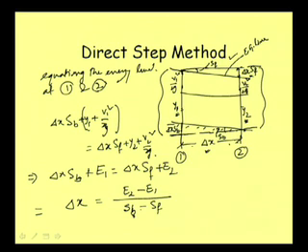So this indicates that this is equal to the energy loss delta E divided by SB minus SF. Well, from this expression, this delta E is basically the energy difference between the upstream and downstream points, and SB is the bed slope and SF is the friction slope.